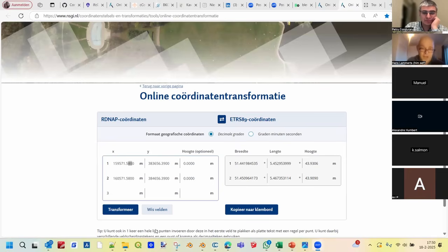I always do my plans in the national grid, so it's fixed in a grid on X, Y, Z. But I don't think it's a smart move when you go to BIM. So every model has its local origin, and every origin has its local placement on the earth. And if you want to bring them together, use a geospatial scene and get these things together. So that's a wise move.